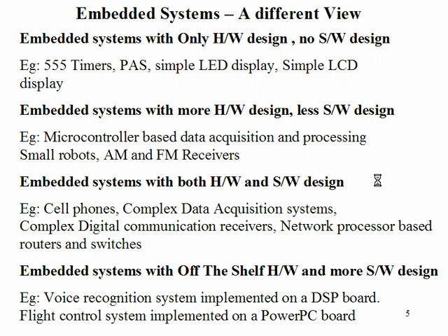But only thing is, when I am writing the DSP processor code, I am going to use a different IDE which is designed for the DSP processor, and my C coding will use the registers and counters which are all related to the DSP processor inside. For example, in a microcontroller, the way we use TCON, SCON, which are controlling kinds of registers in the microcontroller, for a DSP processor I'll have a different flow. But the actual syntax, if you see, will be either C code or assembly code.